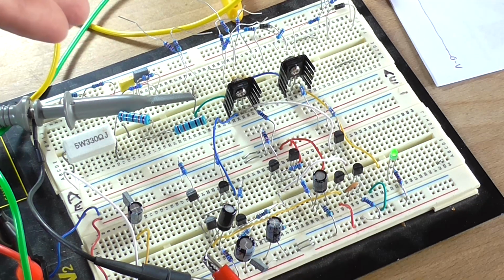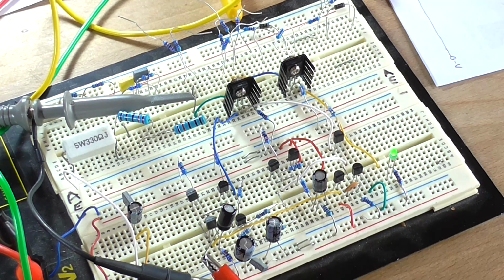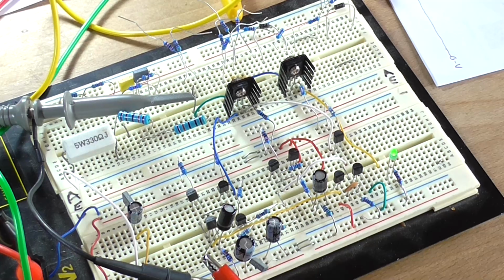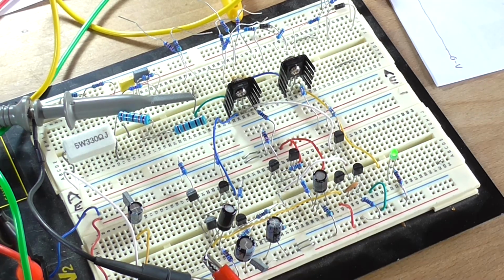Plus it's Class A versus Class AB. The reason why we'd use Class A is because it doesn't suffer from crossover distortion like Class AB does. And someone in the comments of another video said Class A is dead. Like, dude, what? What are you talking about? No, it's not. I agree that Class D amplification is the way that we're doing it now, like with subwoofer amplifiers and stuff like that.